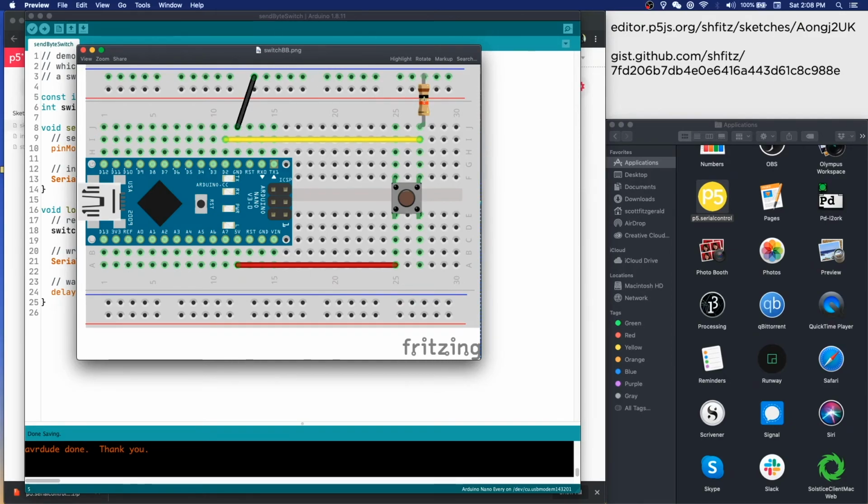And on that same pin, we've got our pull down resistor right here. This is a 10 kilo ohm resistor that I've connected to ground. So remember, the purpose of this pull down resistor is so that your microcontroller has a reference to ground, so you get accurate readings when you're interacting with your circuit. So this is the circuit right here,